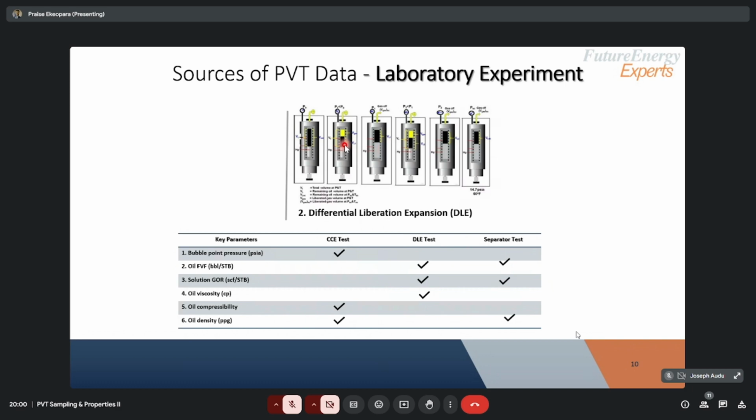Then bubble point, we said BO is the volume of oil at reservoir condition to that at stock tank condition. So in differential liberation, how it works is this. The volume of oil that we want to bring into the system, into the cell, for experiments, that volume we regard to be the one at reservoir condition. So we keep it, we take note of it, then keep on removing the gases, till we get what we call the residual oil, and that's the VL here.